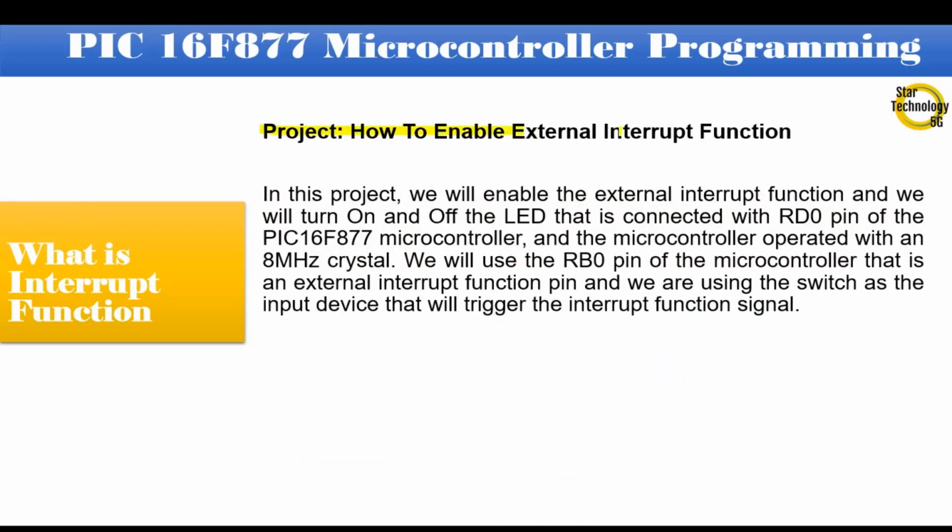Project: how to enable the external interrupt function. In this project, we will enable the external interrupt function and turn the LED on and off. The LED is connected to the RD0 pin of the PIC16F877 microcontroller, and the microcontroller operates with an 8 MHz crystal. We will use the RB0 pin of the microcontroller, which is an external interrupt function pin, and we are using a switch as the input device that will trigger the interrupt function signal.